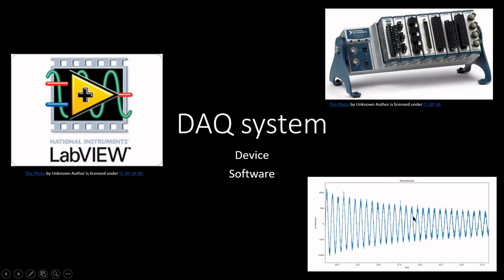So why are these glitches there? This is because any data acquisition system has electrical noise. Basically, they are built upon sensors. A sensor, while sensing the physical parameters, also provides some random values. Those random values are added to the signal and disturb it, so you need to filter them out. I'll explain it very soon.